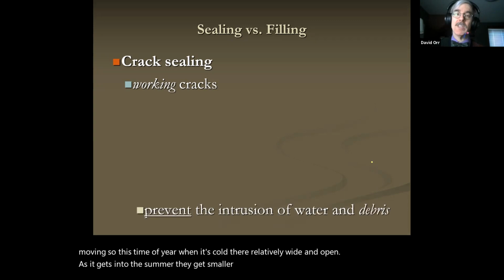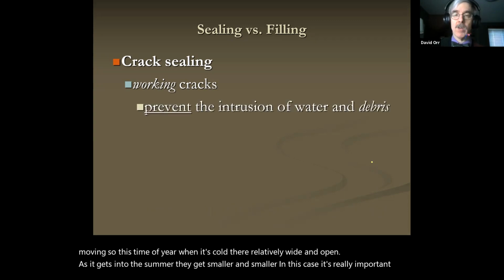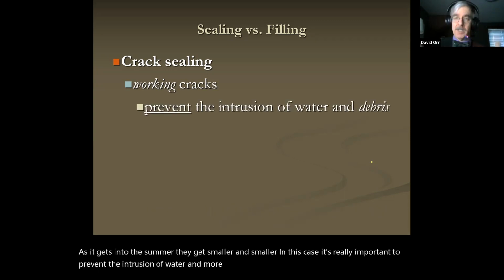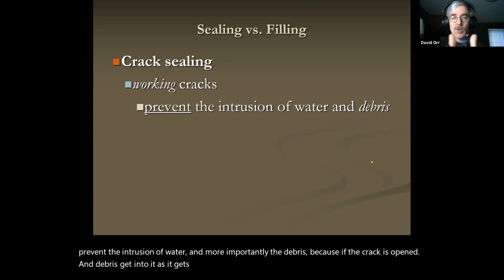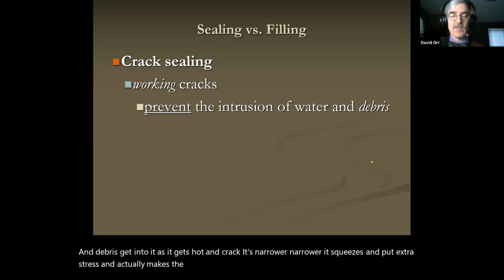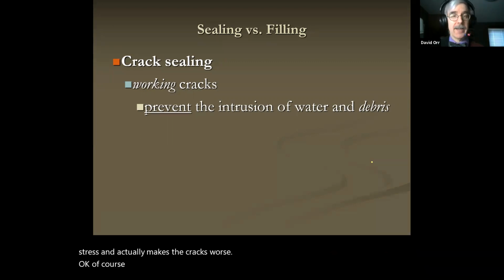In this case, it's really important to prevent the intrusion of water and, more importantly, the debris, because if the crack is open and debris gets into it, as it gets hot and the crack gets narrower and narrower, it squeezes and puts extra stress and actually makes the cracks worse. Okay, and of course, all that water doesn't help either.